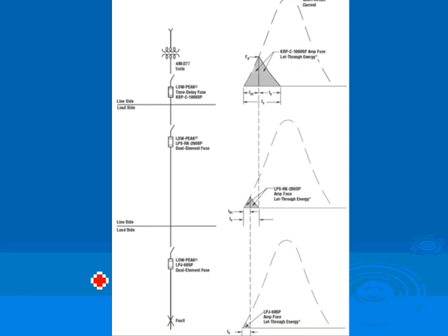when it comes to overcurrent devices, there are two reasons why you have them. Number one, if you have a short circuit or a ground fault or overload, you want them to trip. Every overcurrent device must do that. The second reason that we use them is to limit the energy. If you have a ground fault or a short circuit, do I want to limit the amount of energy coming? Meaning, do I want to burn all the switch gear? If I have a short circuit, half of the switch gear, do I want the PPE? If somebody's working right here, do I want him or her to wear category 4 PPE or category 2? Both of them are acceptable in the NEC code book.